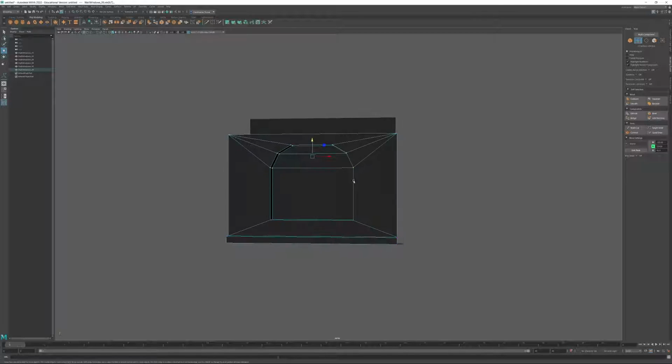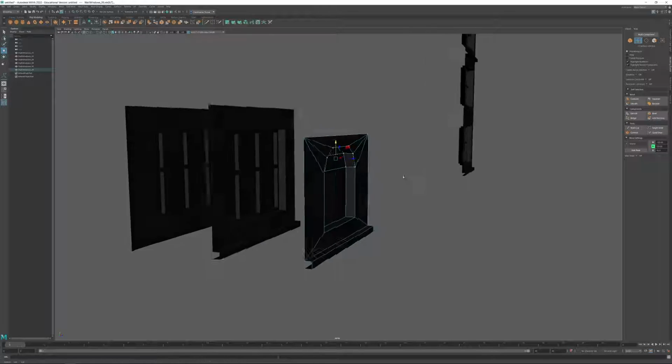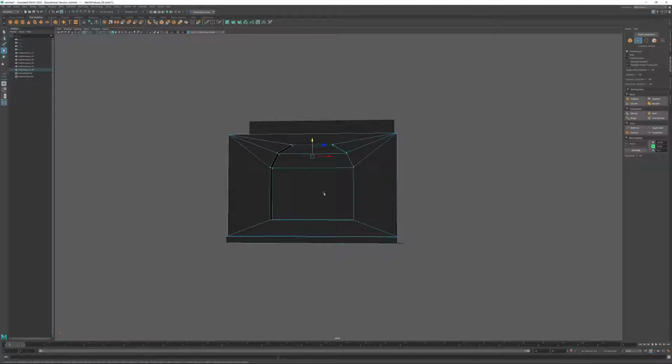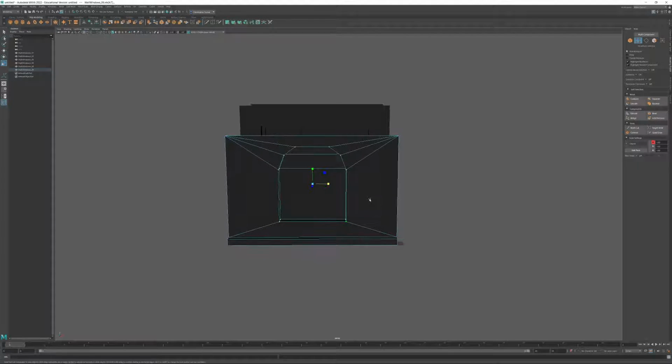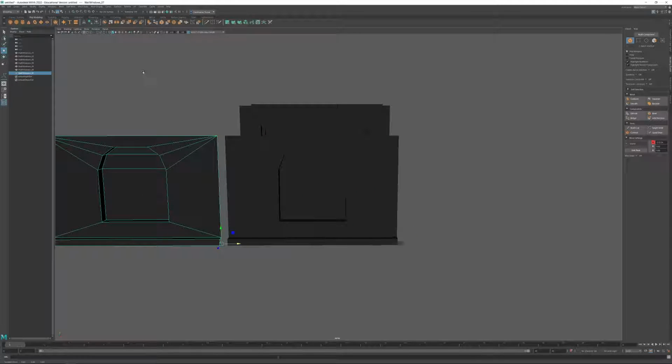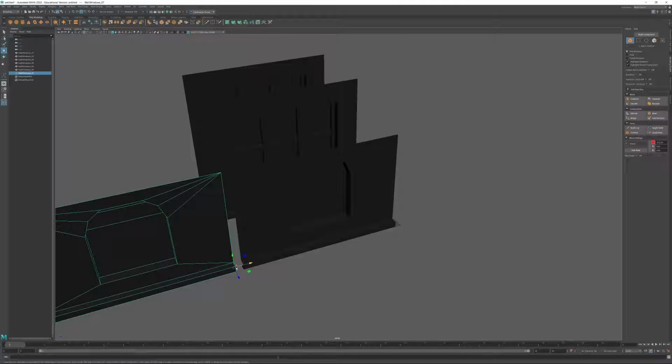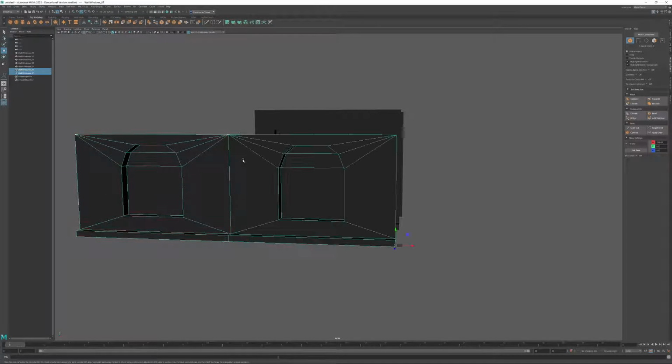Now, at this point, the window's looking pretty short and squat, which is not really what I wanted. And I would have preferred this to actually look a little bit better. So watch this. I'm going to select the arched window and I'm going to scale it in until it's a little bit thinner. Maybe something like that. Then I'm going to clone this piece, holding shift and dragging. I will turn on my vertex snaps and we will snap it to the piece beside it.